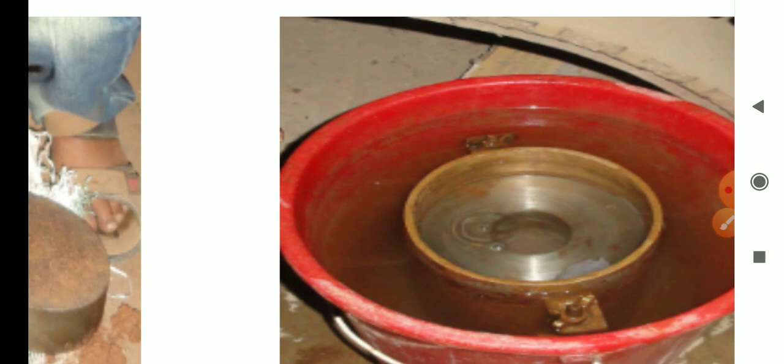In the unsoaked condition, directly the entire assembly you place in the loading assembly, conduct the experiment, and find the CBR percentage. But in the soaked condition, the assembly has to be kept in water for a period of 4 days. After 4 days we conduct the experiment. The reason we keep the entire assembly in water for 4 days is that the soil may contain clay particles.